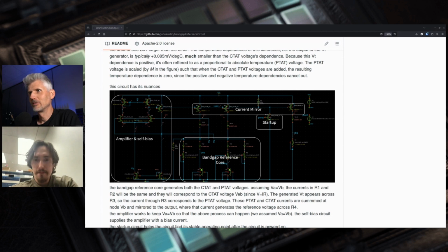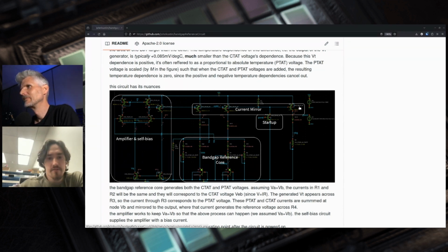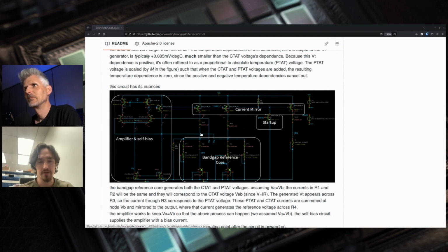And then that current mirror, is that a kind of power supply for everything then? I think in a way it's, I like to think of the current mirror in this, aside from sending a copy of the current back to the reference core. I guess starting with the current mirror that goes to the reference core. The point of that pair of mirrors is at like a quiescent point at the good point of negative feedback. Like what is the desired voltage at VA and VB, and what is the expected current that you designed to go through the BJTs. And so those two PMOS transistors are in the current mirror to facilitate that DC operating point. And then the output, the final PMOS on the very right, that goes straight to a resistor.